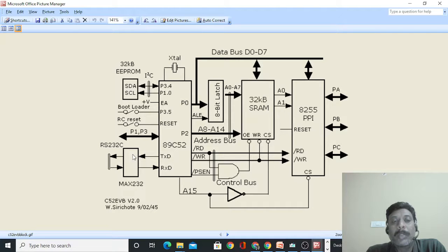So what you can do is implement a program that starts at the RAM location, say 8000, relocate the vector table to start from the 8000 address, and then download that program into SRAM at the 8000 address, and then jump to that 8000 address. So it starts running your application program. So it's a kind of a development board.